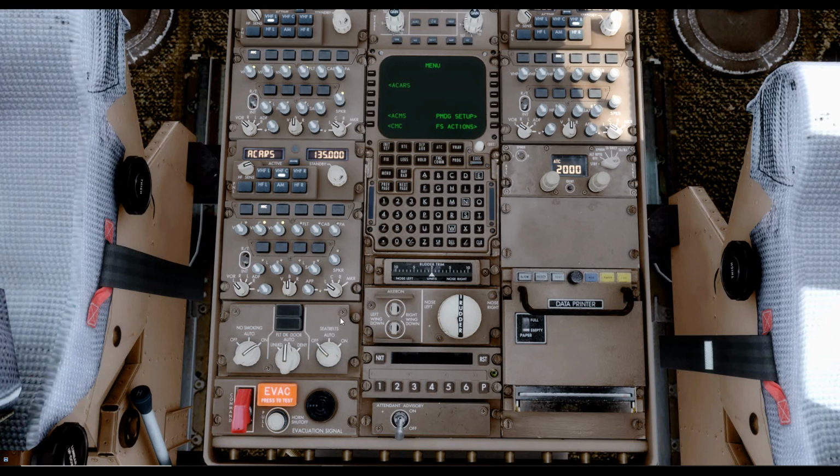And then we would finally test the evacuation command feature. We'd get on the PA and we'd warn the cabin crew that we were about to do the test, which sounds the evacuation alarm in the cabin. And this would also serve as a test of the PA. And once we'd done that, then the cabin crew could call us back to tell us that the PA and the evacuation signals are working correctly.